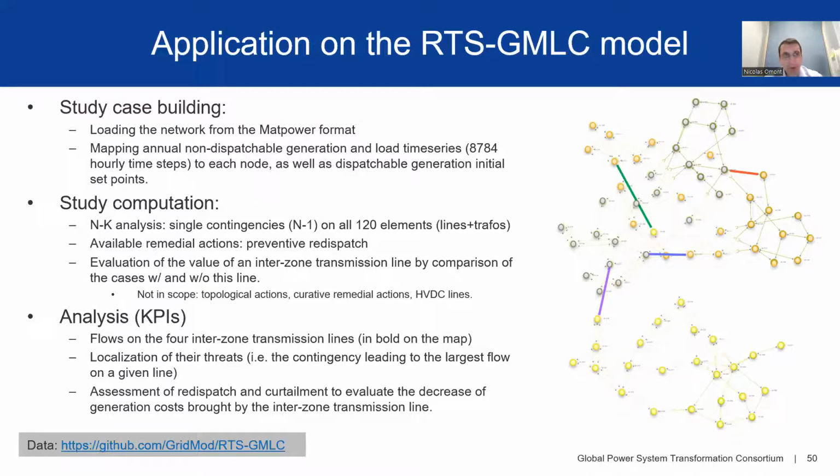Then we finally evaluated the value of an interzone, interregional transmission line by comparing the cases with and without this line, so that we can see if by adding the line you have less redispatching, or if by removing it you have more redispatching.